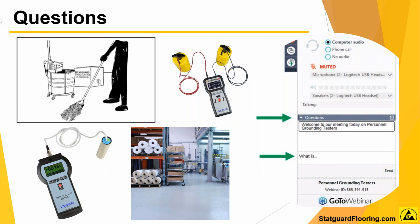Right. Let's talk a little bit more about that too, because one of the questions is how many test areas do you need on an ESD floor to do your periodic verification? Is there a number, or do we have a recommendation? The recommendation would be to pick the high traffic area. That's going to determine more than any other areas being tested. I would start, as an example, with the ESD floor finish type of floor to test your high traffic areas. That's going to determine how quickly your floor is being worn and when you would need to schedule your next maintenance.